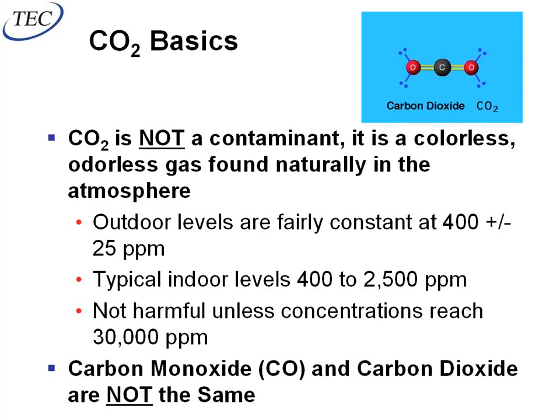So CO2, as hopefully most people on this webinar know, is carbon dioxide. And carbon dioxide is completely different and totally unrelated to carbon monoxide. I bring this up because on a daily basis, people confuse CO and CO2. Today we're talking about CO2, carbon dioxide, which is a byproduct of humans breathing. CO, carbon monoxide, is a byproduct of incomplete combustion. So we're concerned about CO in parking garages and boiler rooms and things like that. CO2 is what we're looking at in terms of the occupants in the space and ventilation rates.